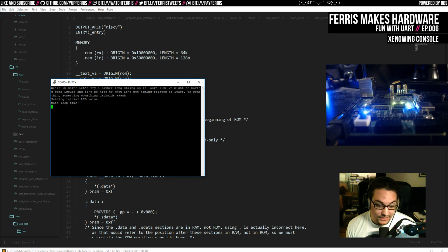Really, when bootstrapping anything like that, it'll be useful to just swap out the code faster, because it's like 5-minute recompiles already, just recompiling the hardware. And especially as we move into things like building the rasterizer, I know I'm going to want to prototype that on the CPU. And after setting up a lot of the simulation stuff, it's feasible to do a lot of that in a simulation environment, but it's not going to be real time by any means. So I'm thinking that having a way to reload the software on the FPGA in a really quick manner is going to be really valuable.